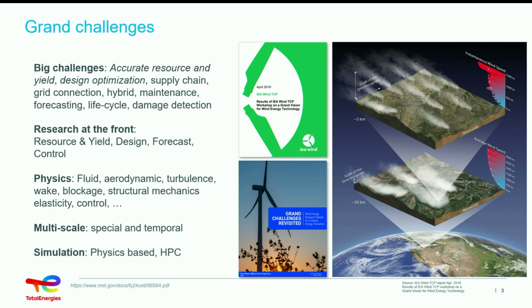But there are also new aspects we now want to understand, like the blockage effect, the induction factor in front of the turbine or at the scale of the farm. With very high density farms offshore, we also have deep array effects, interaction with the upper atmospheric boundary layer, and effects with low-level jets. So a lot of effects to understand.